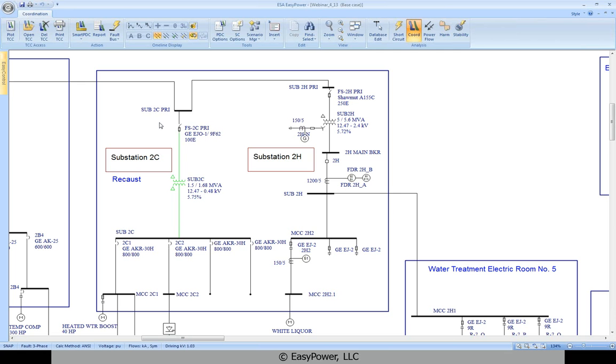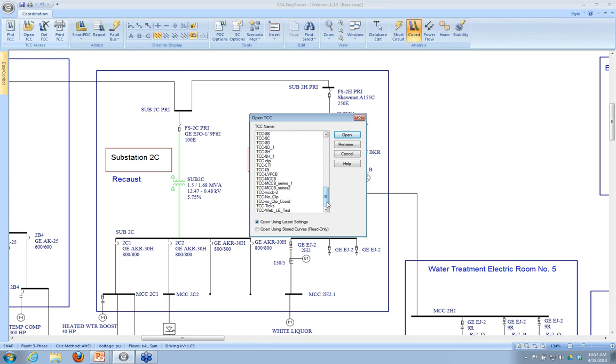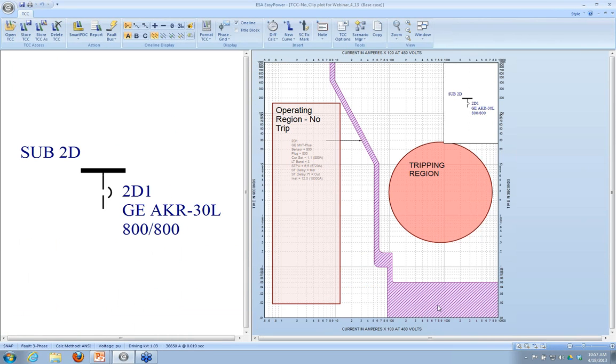So let me go back. Let's look at a typical manufacturer's curve I get for this 480 volt MicroVersaTrip Plus trip unit. So this curve, once I get on the instantaneous trip or the short time trip, it just keeps going, right? It doesn't matter. My manufacturer's curve goes on forever in terms of the magnitude of the current. So it doesn't provide us a lot of information about what the actual maximum fault current is going to be.